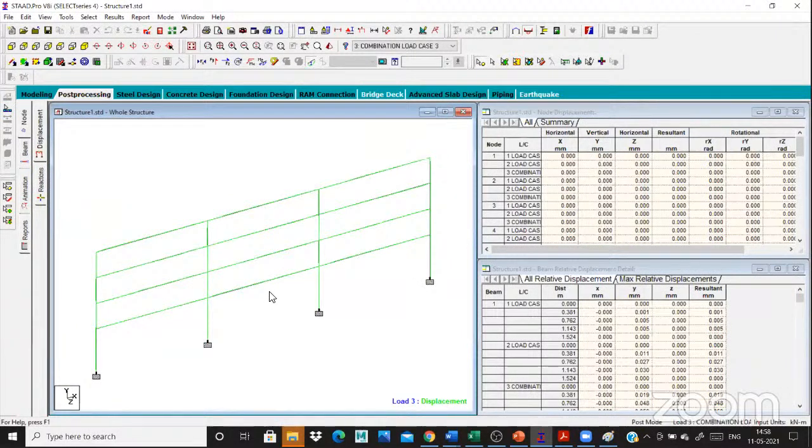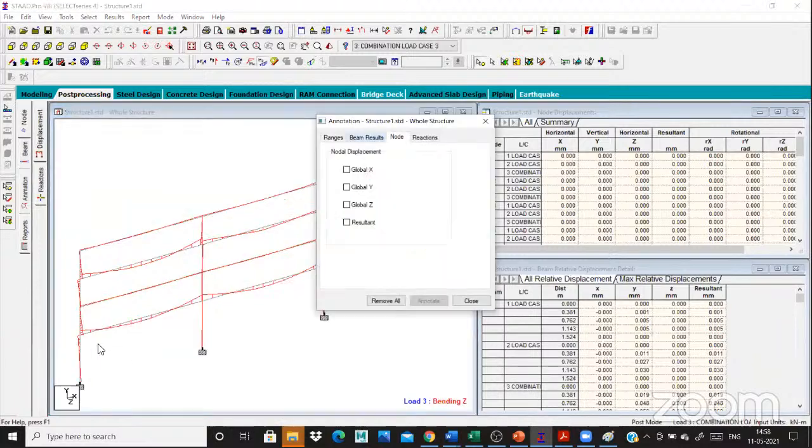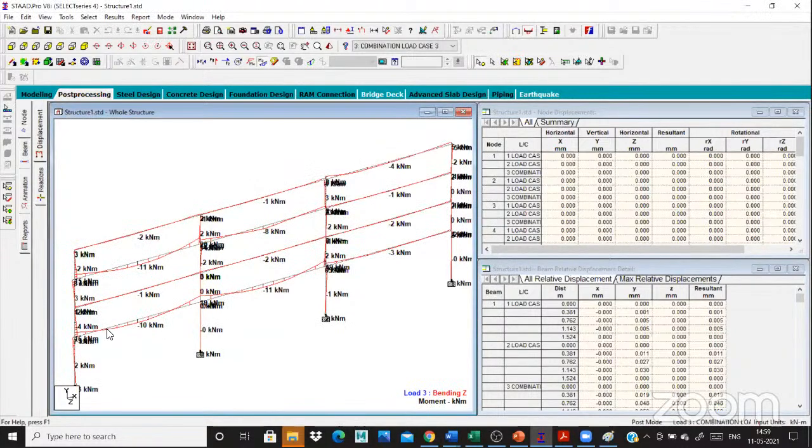See this value, this is 11 kilonewton, 10 kilonewton. You take this as your beam is designed under the moment condition. Automatically Mu equal to 10, you provide Mu as 10, and you will calculate using the design formulas. Okay, now understand, the same procedure will be followed in STAAD also.